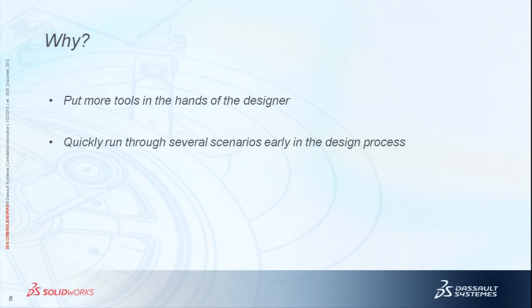And I've run it a few times, so I know that it's about $2. So it's not a huge amount since we're only running 15 parts. So $30. But that would give me a good guide to, well, I know that it's okay at 12 gauge. I might want to run some analysis if I drop it to 14 to make sure it's still strong enough. Do I want to spend that time? Well, to save $30, I'm not going to, because, you know, how much time am I going to spend?